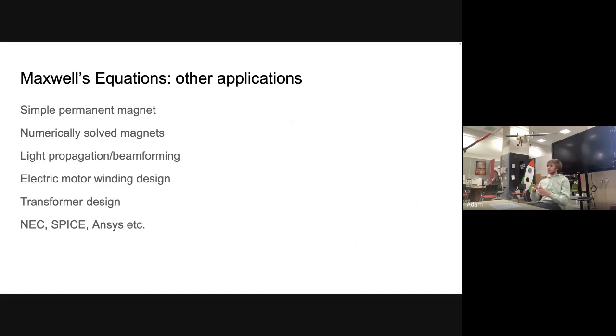Okay, so this is done with cars. They have loops of wire in the road that emit waves. Your car picks them up. Eddy currents are induced in your car, and based on how many eddy currents there are, how much load it's putting on this source, it can deduce if you're a truck or the size of your vehicle. It gets more induced currents if it's a bigger vehicle. But I think you can get precise with it.